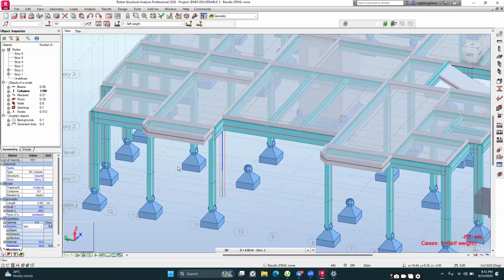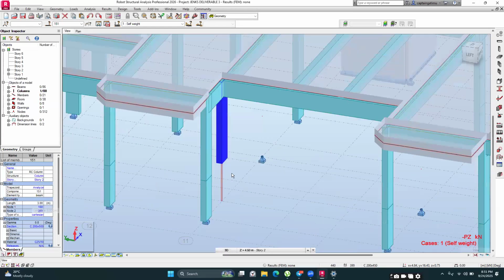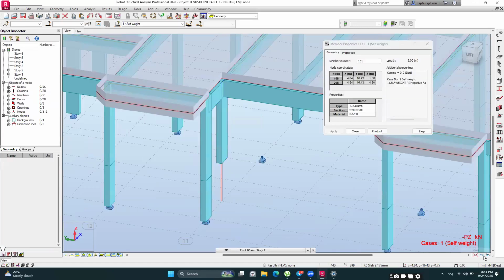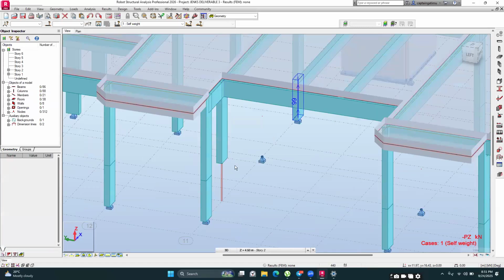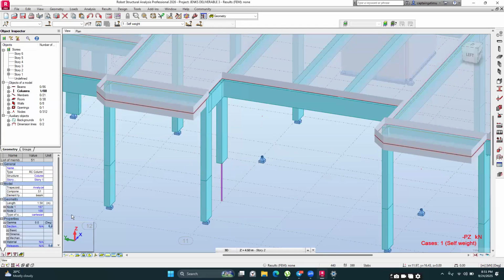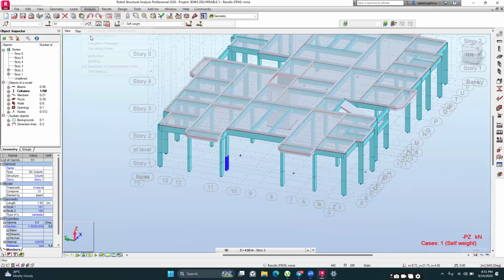If you have this, just select that member, click on this drop down and select a suitable replacement. If it's that section there, replace it with a column, and for this other section, replace it with a similar or suitable cross section. That's how you do it. You just select it, go to the properties panel, and you get to see it. I want us to run another verification so that you can see how that works.